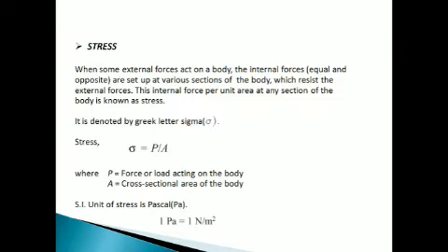Here we discuss about stress. What is the definition of stress? When some external system of forces or loads act on a body, the internal forces, which are equal and opposite, are set up at various sections of the body which resist the external forces. These internal forces acting per unit area at any section of the body is known as stress, and it is denoted by Greek letter sigma.